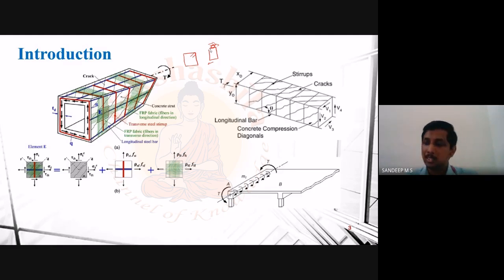It will stay there. So similarly, when this beam is subjected to torsion, we need to tie this up. Otherwise, this will simply move. It will not take any load. So for that, what we do is we just lock it here. We make a loop and close it by forming hoops like this. Okay, and we will put concrete around this, and inside also there will be concrete, so it will be firmly locked. So once you have a twisting force, this steel will actually take up the stresses. Are these things clear? Any doubts, anyone?